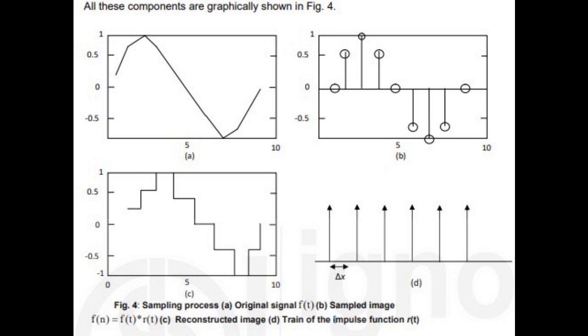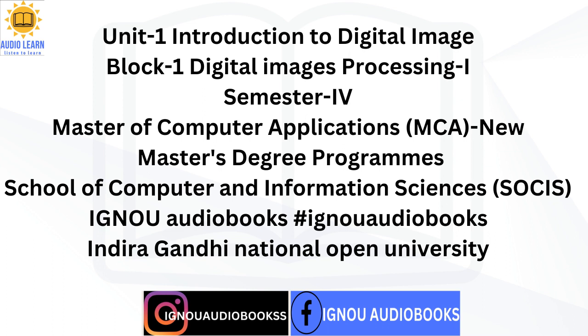If the size is very large, there will be a lesser number of pixels, hence the details become less, which makes the image distracting and meaningless. This is called pixelization error, where the gray level discontinuities at the edges of the pixel become poor. Then the question arises: what should be the ideal size of the pixel? Should it be big or small? The answer is given by the Shannon-Nyquist theorem.